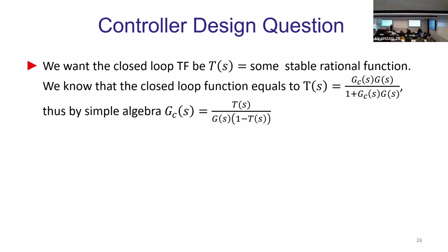So if my closed loop system has all of the poles where I want them to be, I'm good in terms of design, okay? I designed a good system. This is what you did in root locus multiple times, but you played with all these values. Forget about all these values, just decide where you want the poles and zeros to be in closed loop. When you know where you want them, you can write the closed loop transfer function, stable, with all the characteristics wherever you want them to be, beautiful T of S.